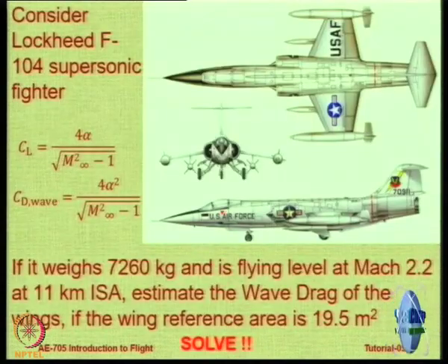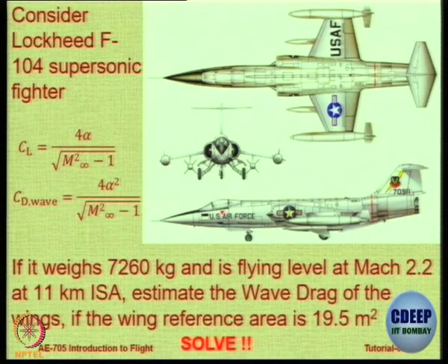If you have any queries or questions, you can ask me. First of all, I want to know the procedure. How will you solve this question? What do you need to estimate the wave drag? So tell me, how do you get wave drag? Because you said you know lift. Yes, lift is equal to weight in level flight. So because W is known, lift is known.